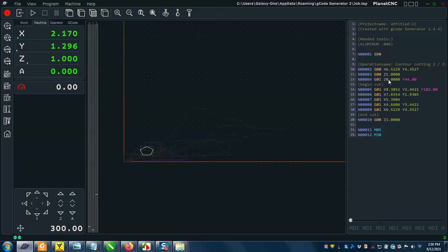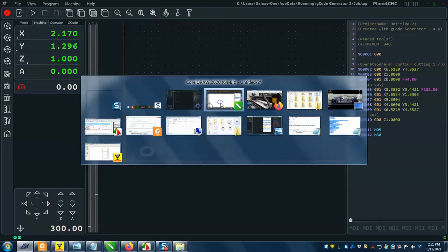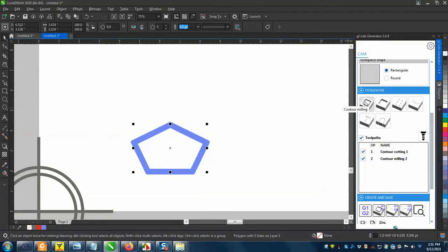But anyways, it's this one that says, notice that the first is the movement of the machine, then the Z lift for the safety height, and then this guy right here, if it's negative, it's going to trigger an error right here. So that's why I don't like using this section right here. But the contour milling works just as well.